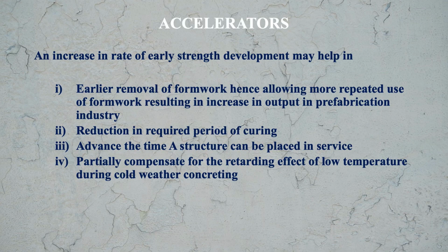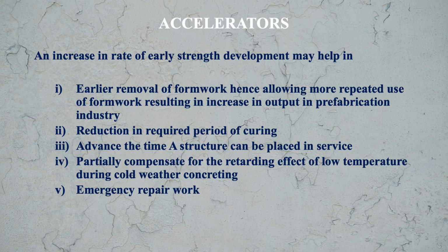Then also it can partially compensate for the retarding effect of low temperature during cold weather concreting. In cold weather concreting, due to low temperature, a retarding effect is there, meaning setting slows down. So here, by using these admixtures, we can compensate for this retarding effect in cold weather concrete. Then by using this, we get an advantage also that we can do emergency repair works quickly.